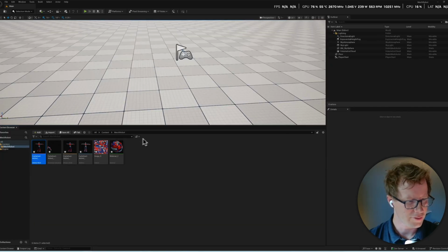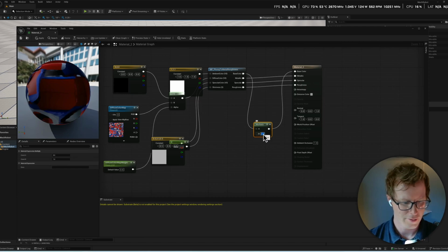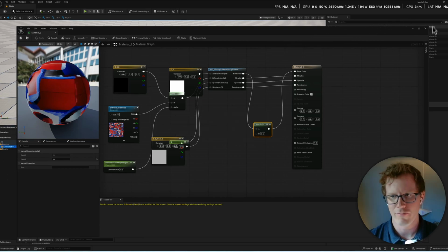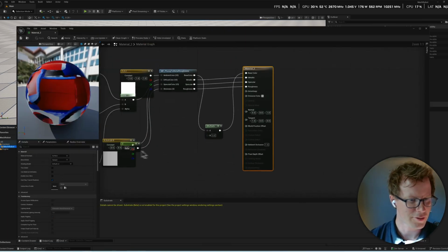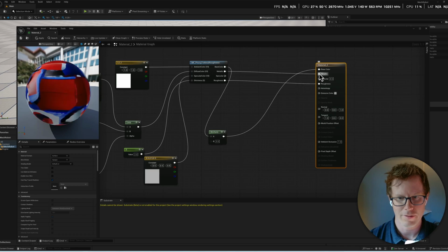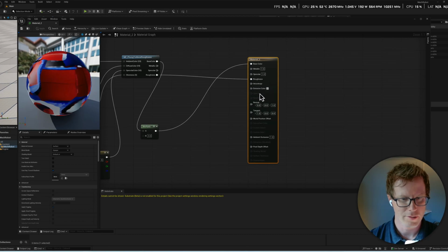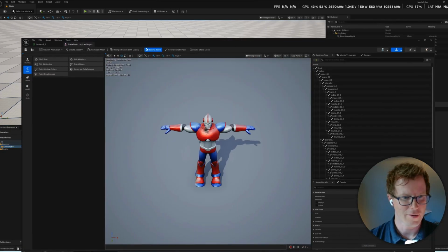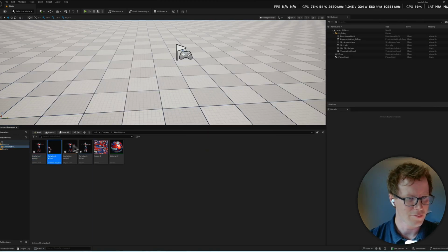For Unreal, what I've noticed is if I come into the material editor, I'll add a multiply node on the base color, and then I crank it up to like 2, 3. It makes the colors more vibrant. There's the skeletal mesh. Cool. And because he's a robot, I want to make sure he's a little bit shiny. So on the metallic, break off this one. I'm going to make my own. Just make the metallic 1. I'll disconnect the roughness. So now I've got a metal robot. It's looking nice. The animation is right here.